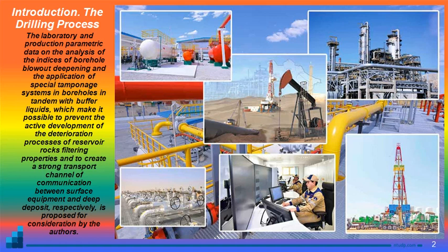It is the perfection of the work on washing, preparation of the wellbore for the descent of the casing string, annular cementing and opening of productive horizons that will ensure obtaining high technical and economic performance of hydrocarbon raw materials extraction.